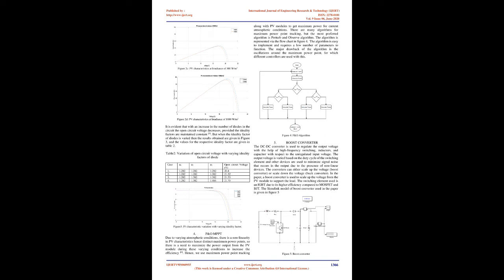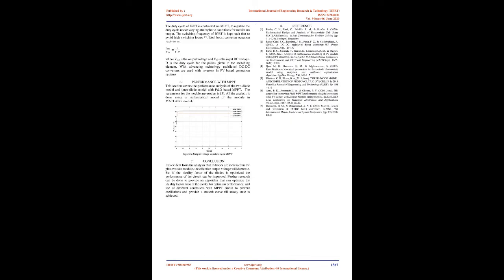The algorithm is easy to implement and requires a low number of parameters to function. The major drawback of the algorithm is the oscillations around the maximum power point, for which different controllers are used with it. Figure 4, P&O algorithm.